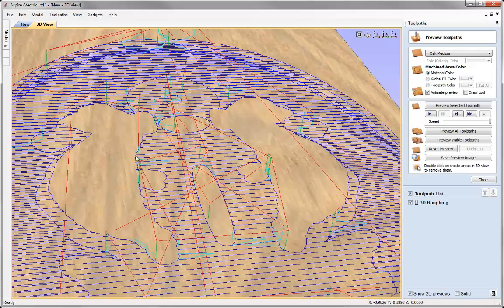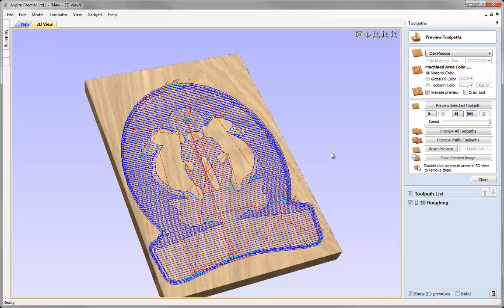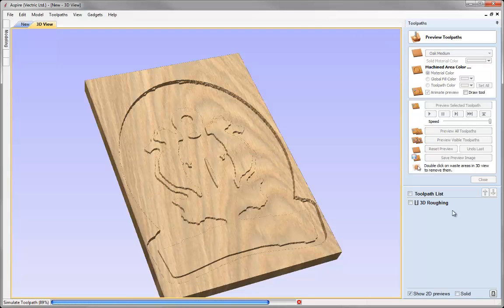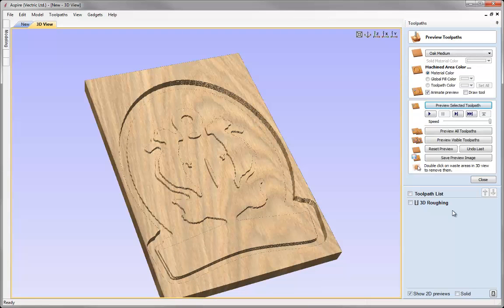And that's just going to calculate the toolpath for us, and we can see if we look closely the zigzag there of the ramp coming down into the job, so that's just going to lessen the force on the tool, or certainly the force on the bottom face of the tool as it ramps down and into the part there, and so hopefully reducing tool wear and also perhaps reducing some movement in the tool as it tries to move vertically into the material. Now we can go ahead and preview that, take a look. I'd expect everything pretty much to look as it did in the previous version of the software.